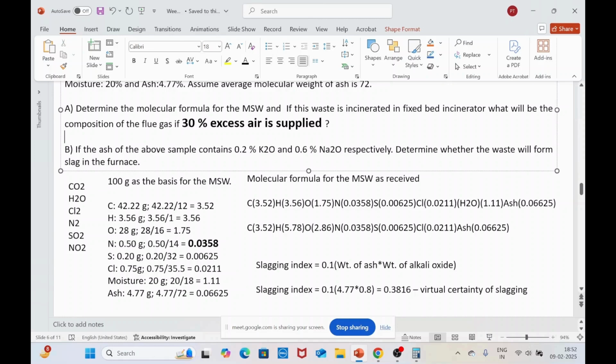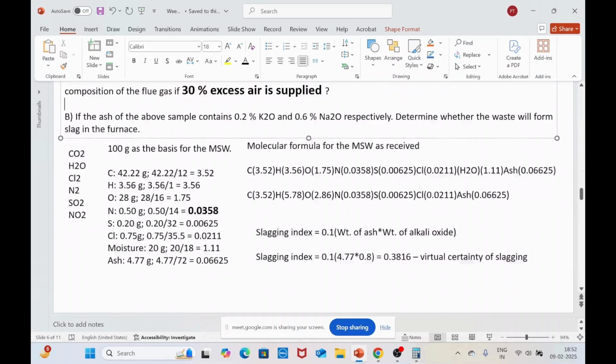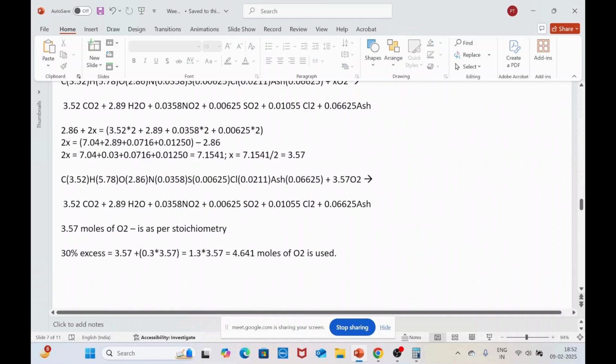Here it is not written only O2, it's also that nitrogen gas is going to participate. It depends upon the way you can assume in the course, in the lecture slides. If you see, it is taken as 4 is to 1. They have taken nitrogen as 80 percentage, oxygen as 20, or you can also take 79:21. I am going to go with what is within the scope.